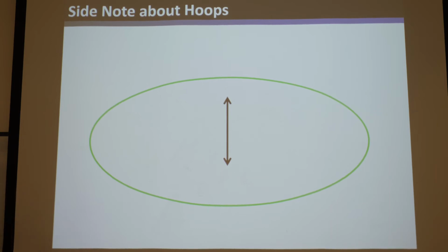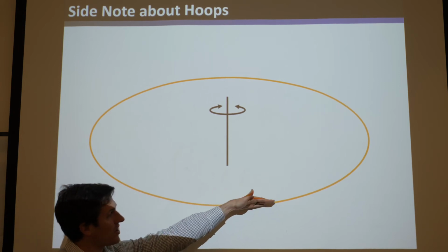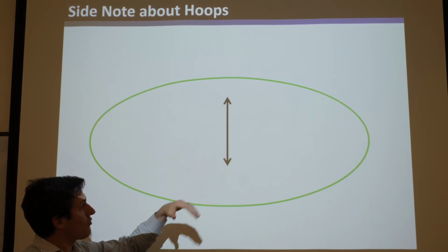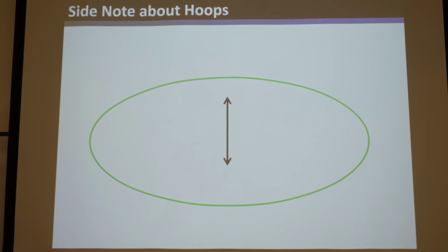So okay, and by the way, also if you take obviously a wrench with the non-zero, non-infinite Q to infinity, it also makes a pure moment, just like blue and orange hoops make pure moments. Red and green hoops make translations. Now, you might say, well, what if I pull a translation to infinity? Well, again, translations don't have locations, so there's nothing to displace or pull.